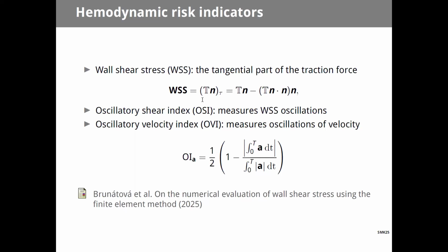Another note is that if you employ the Navier slip boundary condition, the slip boundary condition is in fact a condition that your velocity is directly proportional to the wall shear stress. So instead of this, you can take your boundary velocity to be a good approximation of the wall shear stress. That was investigated in this publication by Jana.